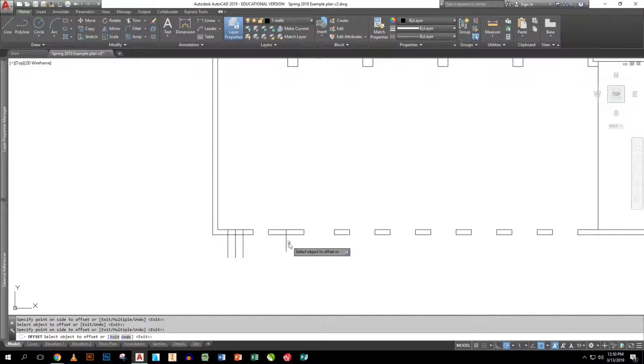That gives me a decent spacing, it looks like, for what I wanted. And it lets me get the look I'm going for. So it evenly spaces it, trim, enter, enter. Trim off the piece I don't want. So that's where my big, long, tall windows are going to go over my stairs from my sketch that I planned. And those are 1.5 foot windows.